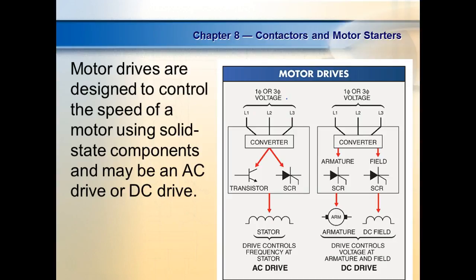But what we're going back to is, this is the symbol for what we call a bipolar junction transistor. And if we operate it, we've got 3 regions we can operate this in. We can operate it as a switch, which means we either cut it all the way off or all the way on. Or we can operate it in the active region. In the active region, it acts like a rheostat. So one region we operate it like a switch, the other region we operate it like a rheostat, electronically controlled.